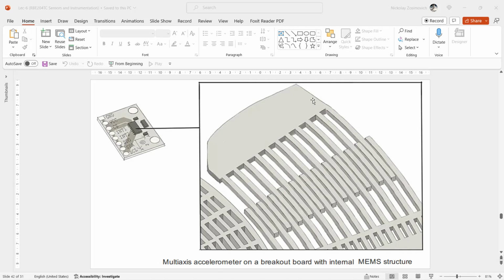This angle sensor combines an inductive principle for the transduction from angle with respect to a fixed magnetic field, to the deflection of a polysilicon micromass, and the capacitive measurement of this deflection. A planar micro machined gyroscope with a balanced capacitive readout circuit. A graphical impression of this micro machined structure, as can be found in gyroscopes and accelerometers, is shown in this figure.